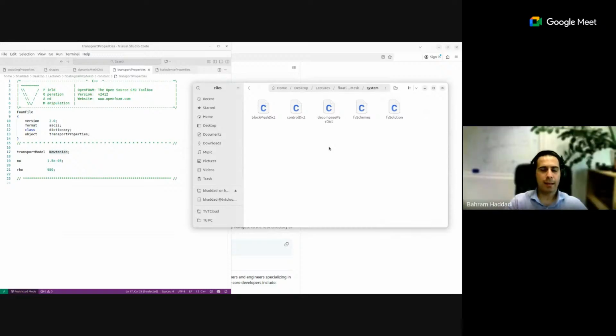Okay, thanks for adding that. I wasn't really aware that the drag model and the models that we have in there are Newtonian ones. But if that's the case, then that definitely should be considered. But if the drag model that we are using can also support non-Newtonian, then basically what we deliver from the CFD side to the DEM is a simple viscosity, and that can come also from a non-Newtonian fluid. So, no limitation from the CFD side. On the resolved one, that's also no problem. But on the unresolved, as Hamid already mentioned, please be careful with the type of models which are used, that they are compatible with the physics that we have at this side.